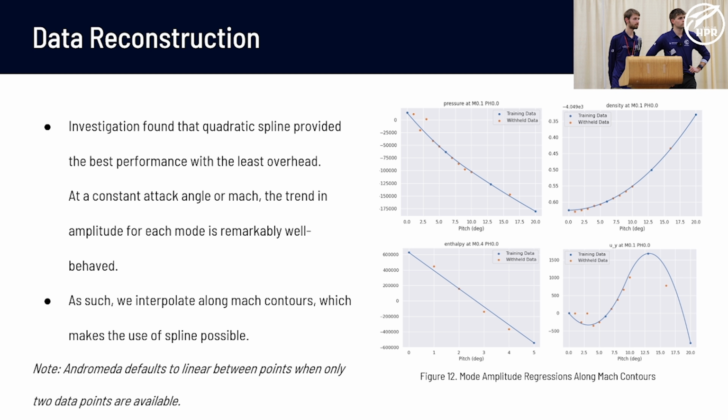And so most of the initial data was initial training data. Basically, OpenRocket is just to gather a template for our drag database. Obviously the rocket spends time at a Mach number, angle of attack, and roll, and we just want to find roughly what this is. We get that from OpenRocket. Then we take those points and solve for them, and we can run a simulation in our inbuilt simulator, which then predicts the trajectory much better, and we can really refine these points.